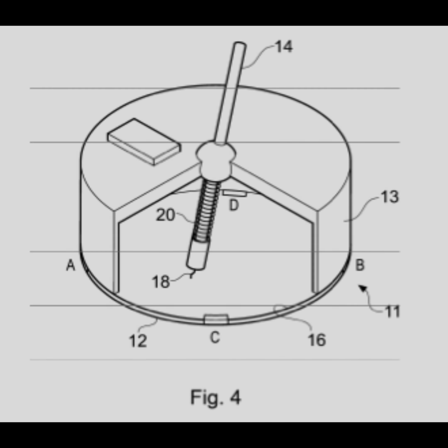As shown in Figure 2, when the stick 204 is pressed against the panel 201, the protective layer 205, the resistive layer 206, and the gel layer 207 are locally deformed until the resistive layer 206 is in electrical contact with the conductive layer 208. The gel layer 207 is thick enough to prevent unintentional contact between the resistive layer 206 and the conductive layer 208, for example, when a user merely touches the panel without applying significant pressure.